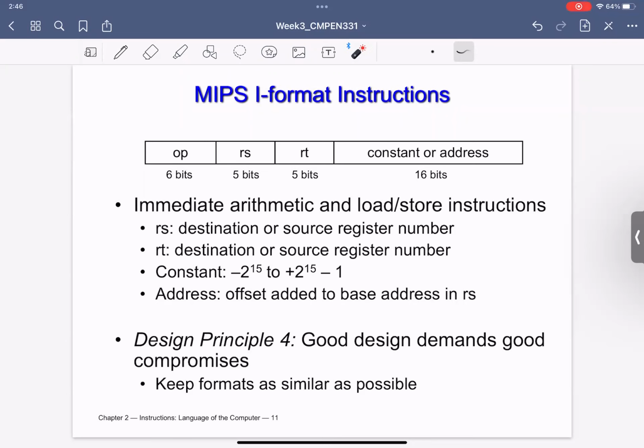So they will just follow that 6 bits for the operand. They need, as we mentioned, 2 places for addresses. So that's why they take 5 and 5. And then the rest is just for a constant. That's what this is, because we have again a 32-bit width inside the memory. And this might change if I give you another problem. Because again, inside the memory, I'm assuming that I can address a word, and this word is 32 bits.